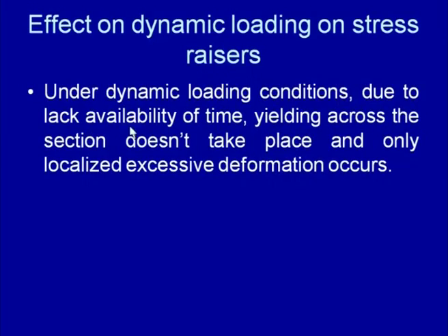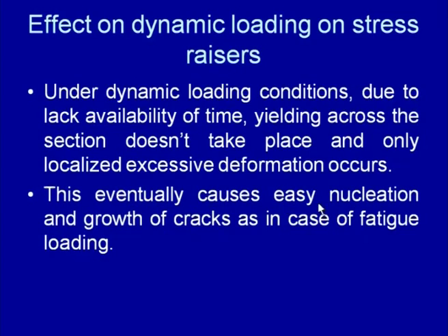While in case of dynamic loading conditions, due to the lack of availability of time, because the rate of loading is high, the yielding across the cross section does not take place and only localized excessive deformation occurs, and this localized excessive deformation eventually causes easy nucleation and growth of crack, as in case of fatigue loading conditions.